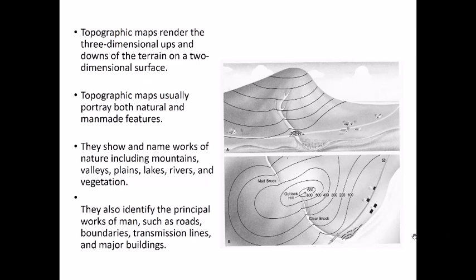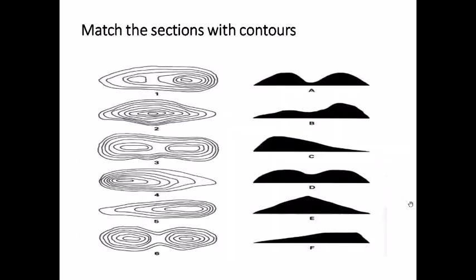So basically, you get an idea about the entire nature of the land that we are talking about by looking at these maps. And also, there's a feature on Google Maps on which you can turn on the terrain, and it can show you these inbuilt contour maps of any land that you want. And similarly, you can see it on Google Earth as well. Even on Google Earth, you can use the software to draw these contours by selecting different points, and by suggesting a contour interval, you can draw these contours as well.